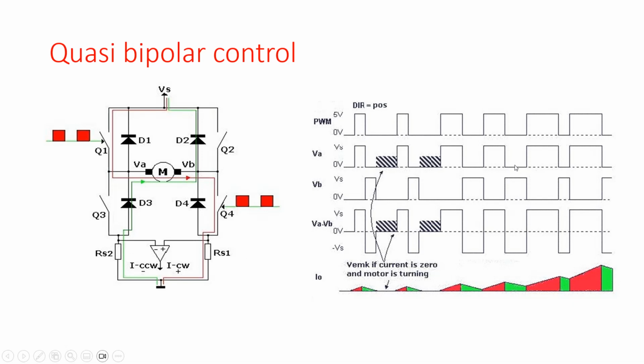That is depicted over here, and current flows through D2 to the power supply, and when D2 also is an ideal diode, then VB is equal to the maximum power supply voltage VS. So VB has a positive value.